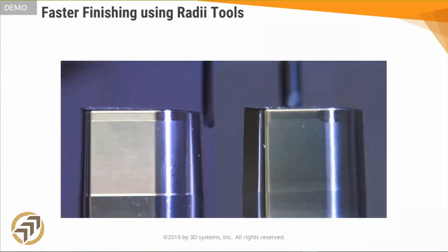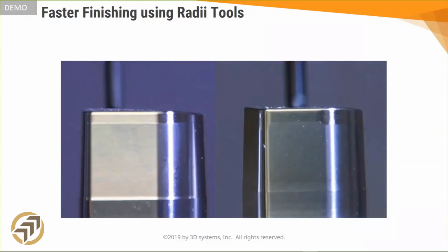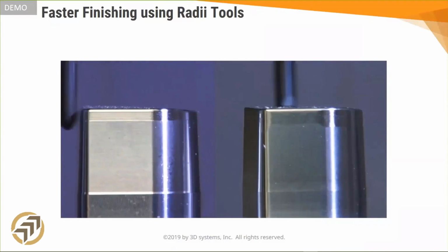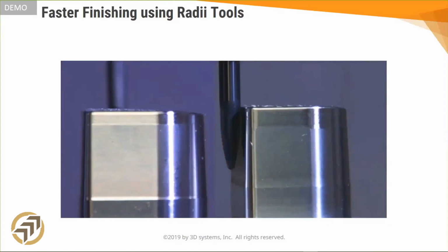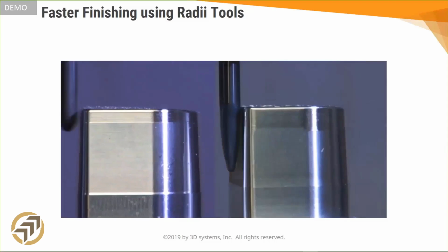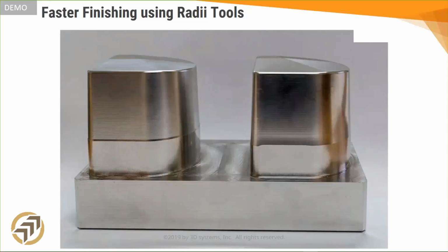A lot of the machining that mold parts require is a good fit for these special cutters. And while they're currently more expensive than regular ball cutters, it's a great way to cut time on the CNC machine. Having the ability to utilize these new cutter shapes is an important feature for your NC software.